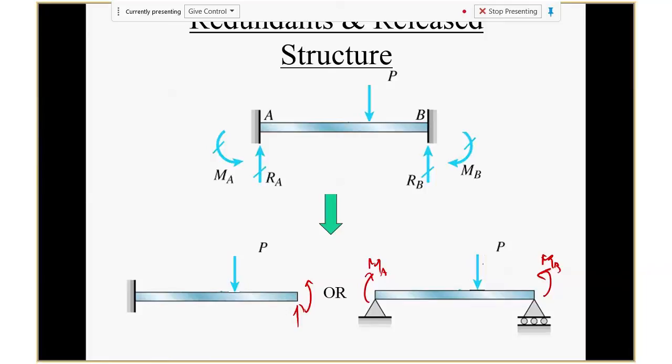You can use superposition, right? Or you can search the table, find the answer, combine it with the superposition, and solve for it. Or another way, you can just write the equation for the bending and solve for it.